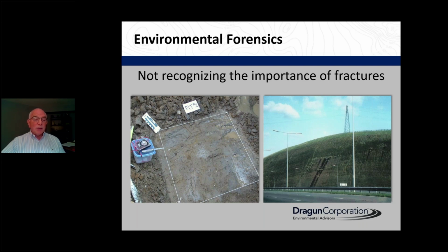The problem is that these fractures are vertical, so you need to be able to intersect them with a borehole that's vertical. You have some problems, and there are ways to get around it. Or if we look at this road cut in rock, if we didn't have this road cut, we would never recognize this fracture where the groundwater is coming out, or it'd be unlikely that we would see it. So fractures are important.